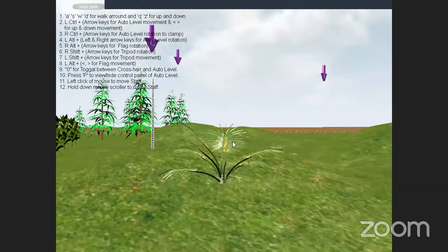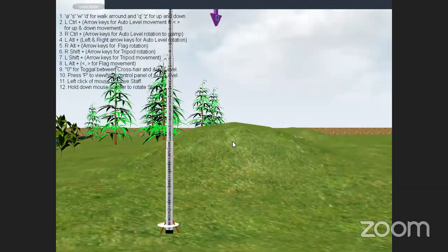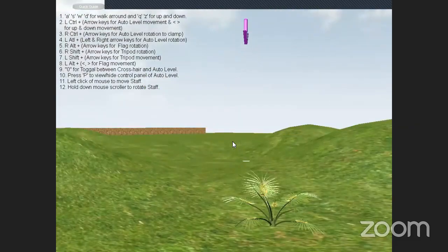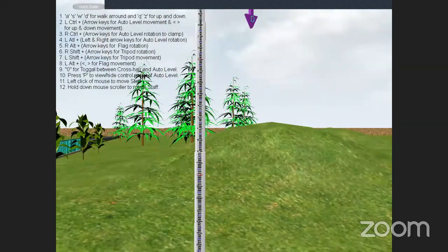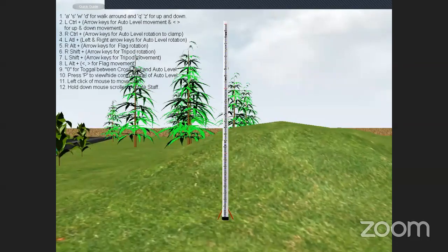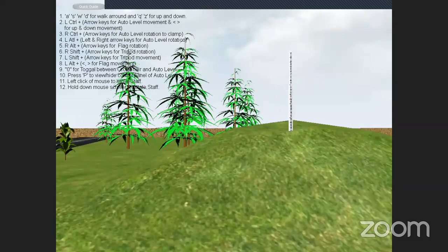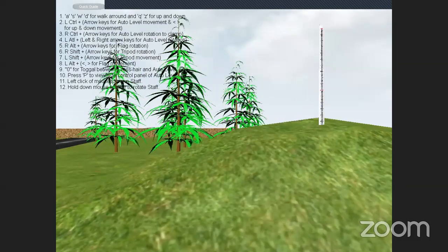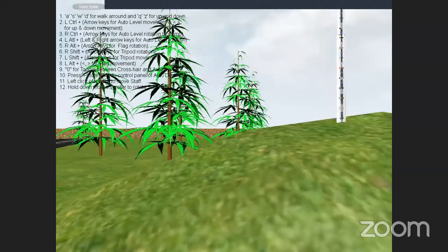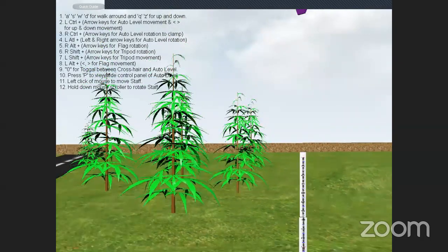Actually, you cannot move the telescope like that. For the time being, I am explaining like this. You have to move the telescope as well as the tripod along. But in an animation, we have the opportunity to move in the same horizontal plane, so nothing will happen. Now with this reading, the third point D may not be visible, so you need to shift the instrument.